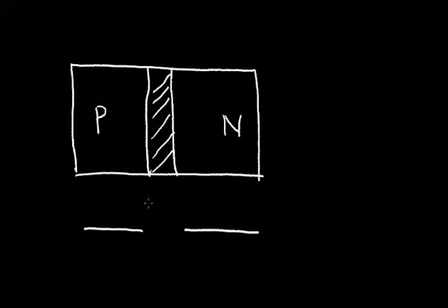So remember the capacitor. So here I actually have a capacitor. I have a P terminal, I have an N terminal. This region can be thought of as a plate on a capacitor. This N region can be thought of as a plate. So I have a plate and a plate. So this p-n junction has the characteristics of a capacitor.